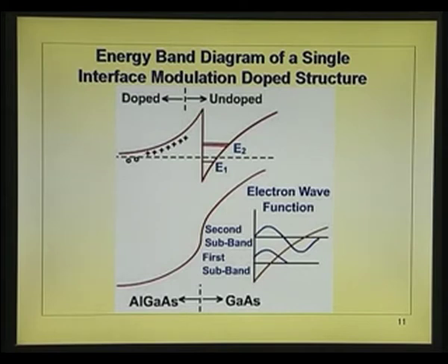You will see here there is a doped layer up to this point, that is aluminum gallium arsenide. There is a small undoped layer here, aluminum gallium arsenide, same band gap, but the dopants are not there. This shows the dopants are stopped there, undoped, and beyond this point undoped gallium arsenide. You get of course the notch here, and how large this notch is depends upon the mole fraction of aluminum gallium arsenide. So, the thin layer you put it here.